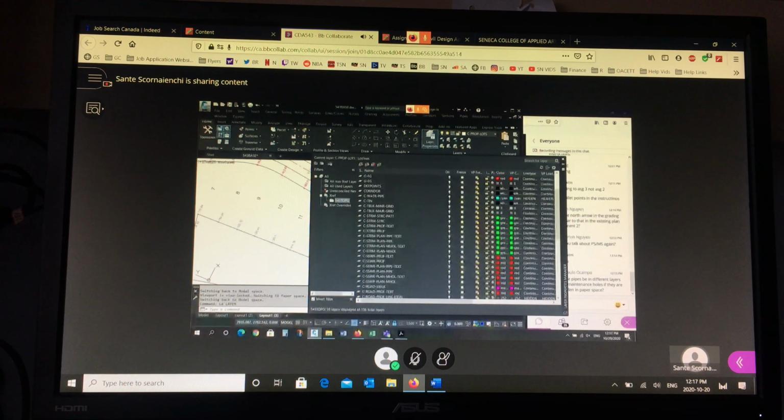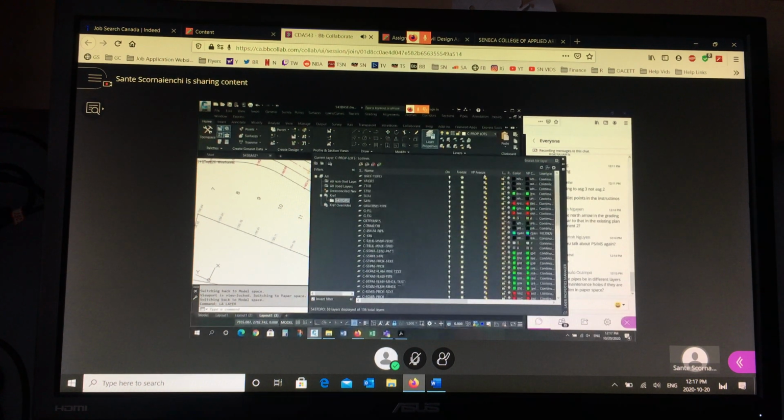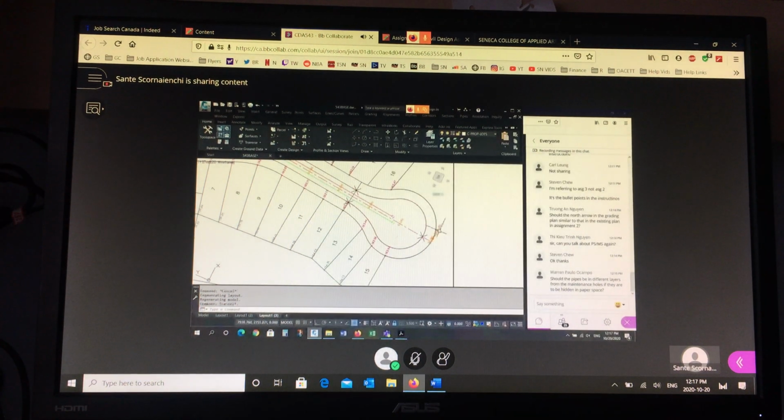You can actually freeze layers in the viewport. Right? So never mind the layer name, I can freeze a layer through the viewport. Or you can freeze it, and that freezes it in every view. Right? So you have to make use of this column so you can do your layer management. Maybe I'll talk more about this tomorrow. You can do your layer management through the viewport.